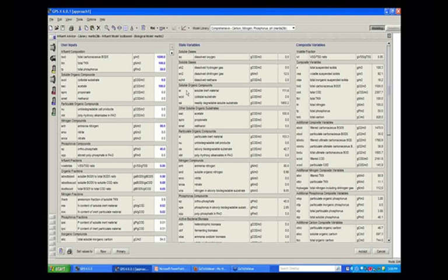As you can notice, this wastewater has a high BOD of 1500, a TKN value of 100, and a TP value of 50. The total COD value going through this inlet to the reactor is 2,307, and we can characterize this as a medium strength waste. You can input all your values here, and we have already done that in this example.